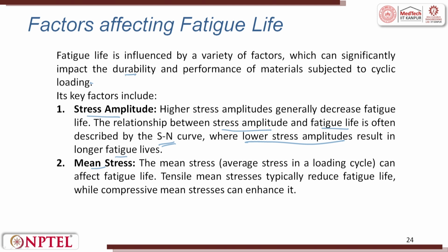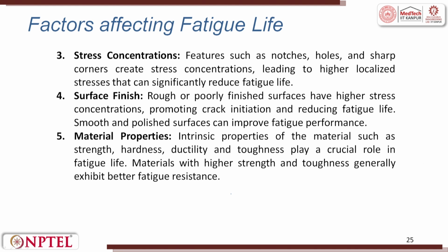Mean stress. Mean stress, otherwise called average stress in the loading cycle, can affect the fatigue life. Tensile mean stress typically reduces the fatigue life, while compressive mean stress tends to enhance the life. Stress concentration is another factor which affects fatigue life.